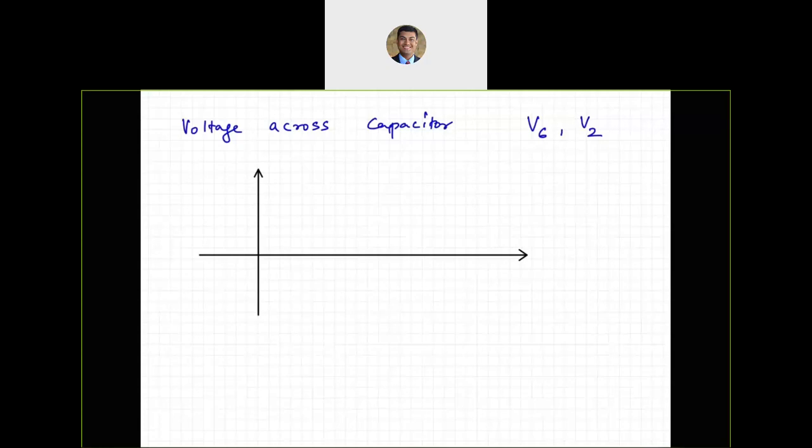So what is going to happen? At the beginning, the voltage across the capacitor is 0, say. It will start charging, and if this is 9 volts, let's see, what is 2/3 VCC? Well, 2/3 VCC is going to be 6 volts, and 1/3 VCC is going to be 3 volts, assuming that VCC is 9 volts.